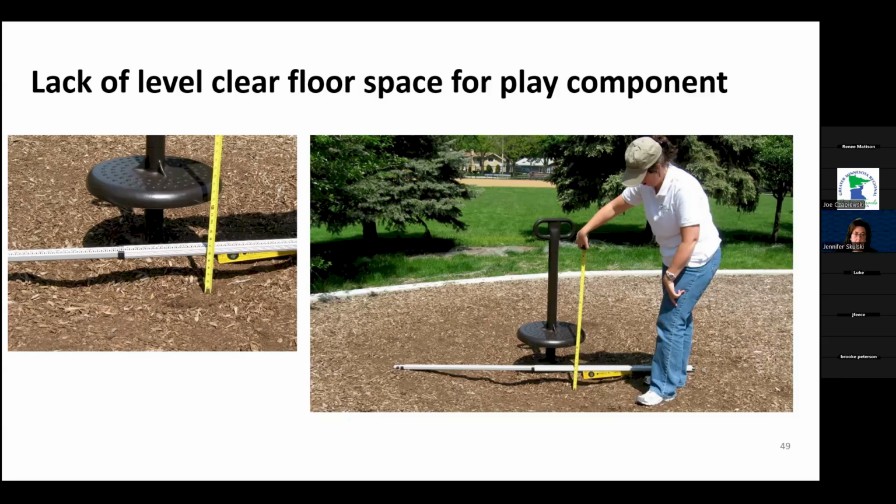to be maintained over time. So you might have heard way back when, 15, 20 years ago, it was very popular for a sales associate to tell you, oh, just throw it in the playground, shovel it in, blow it in, and it'll settle over time and it'll be fine. That's not the case at all. It really needs to be put in layers, watered and compacted at each layer.